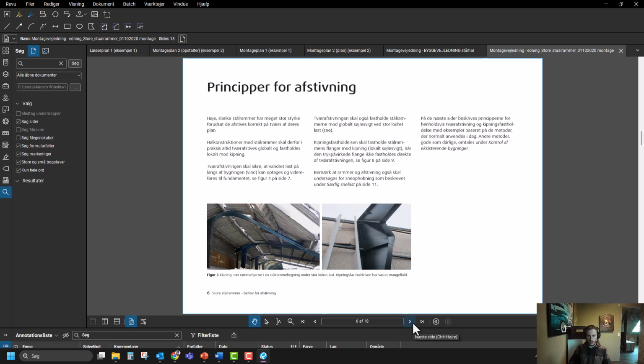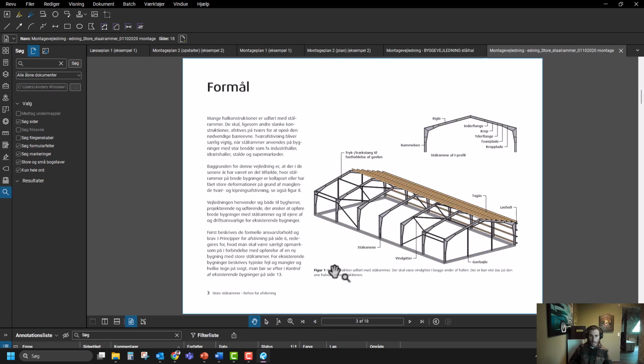Principles for us to install these frames while they're sitting. The first one you put is for the glue laminated frames. Please have in mind how we put it and install it into the point foundation and together, and for that not to tilt over. What do we do in the meantime? We need some kind of material or installation or product to prevent it from that until we put the next glue laminated frames, and then our bars here can actually help prevent the two glue laminated frames from tilting and falling over.